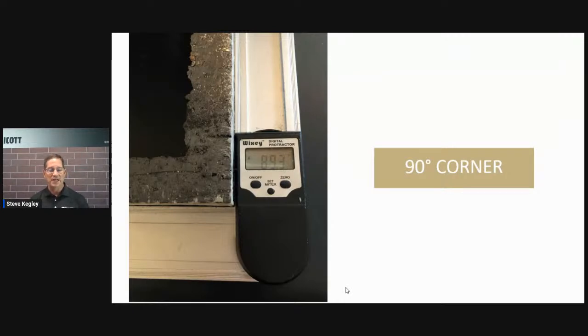If it's not right, any of these thin brick that you find something wrong with when you're measuring it, just set it off to the side on a pallet, hold on to it. Manufacturers will help replace those. It's not a big thing. We can't make exactly what you order at the plant. If you order 11,000 square feet of modular size brick, we're probably going to have a few thousand square feet left over because we can't control it that way.